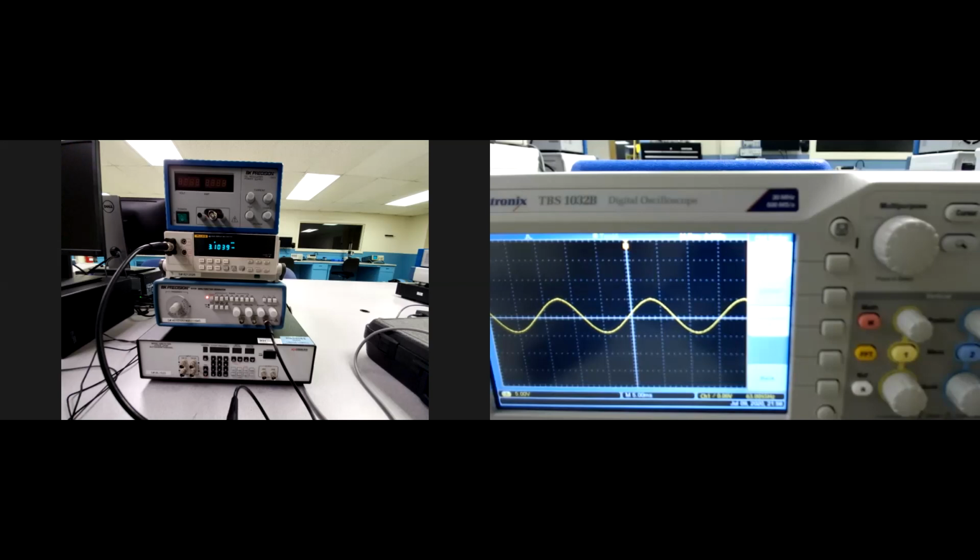Turn the function generator on. Set the function generator to an output of 100 hertz sine wave at the maximum amplitude. And can you read the important note? Important: whenever you generate a new signal, use a multimeter and oscilloscope to check the magnitude and frequency of your waveform. Note that the multimeter outputs RMS voltage for an AC signal.